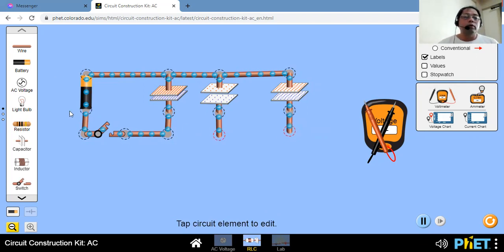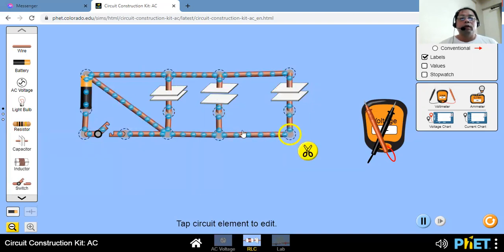So one way to probably discharge them is to have this short circuited. So you can remove the charges there by putting a short circuit wiring. So now they are empty.